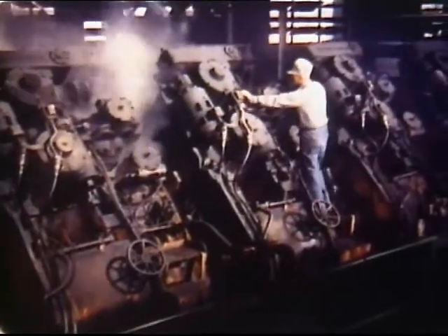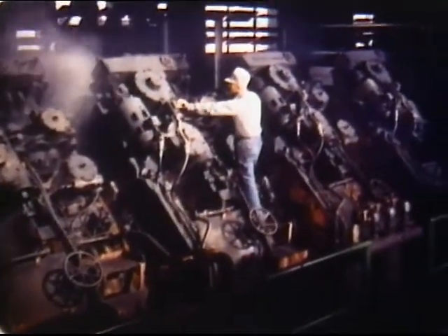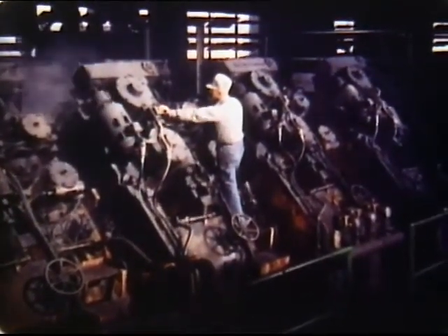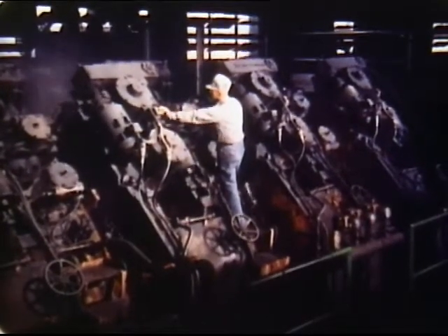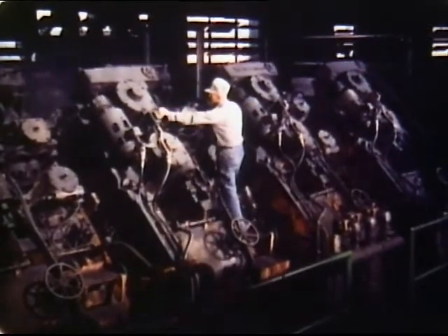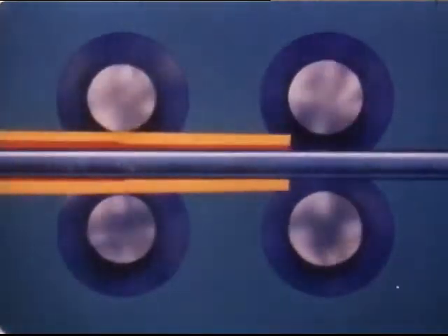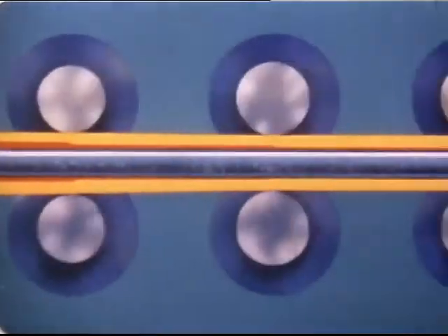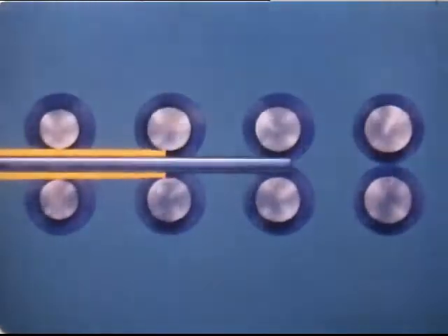It has 9 pairs of semicircular grooved rolls so arranged at right angles to each other that the rolls alternately engage one side, then the other of the shell's outer surface. Reduction of the shell's diameter over the mandrel is the first step. The first 2 sets of roll stands do that. The next 4 sets of rolls reduce the wall thickness.